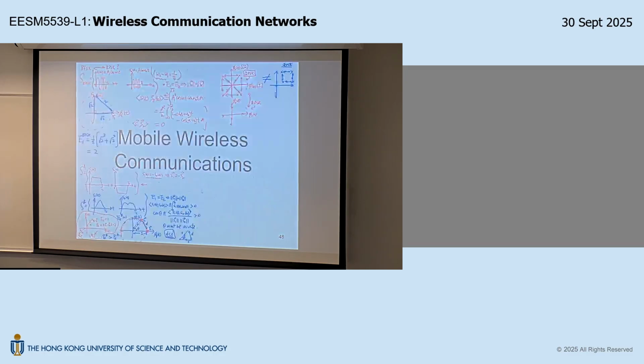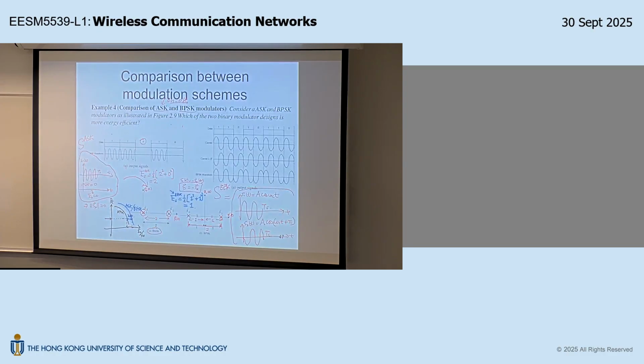Okay, so another thing is, so this is binary, right? So that's why usually when we specify the modulator, it would be much more convenient if we specify the signal set directly using the geometric domain, right? Directly give you the constellation diagram. Because in this case, just using the constellation diagram, you can directly compare the constellation configuration between different designs. So you save the trouble of converting from time domain waveform to geometric points, right?